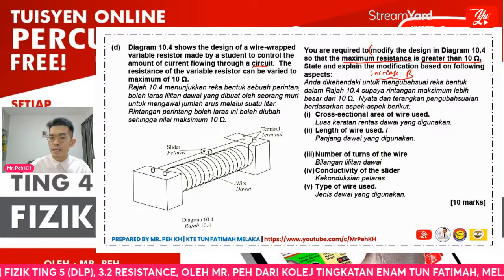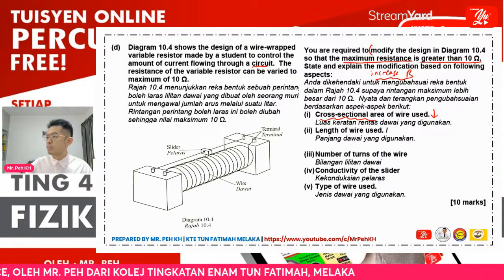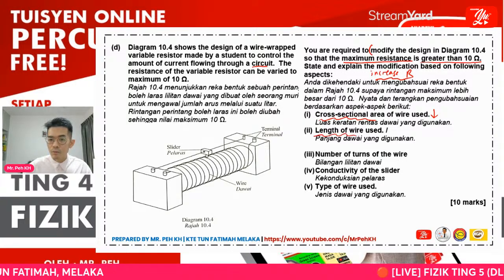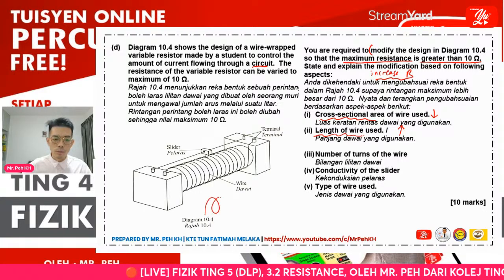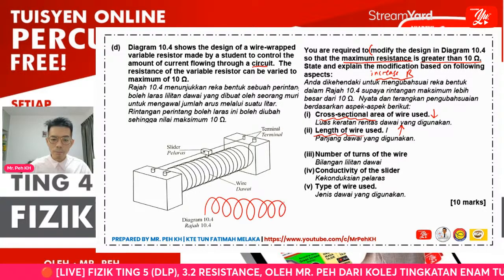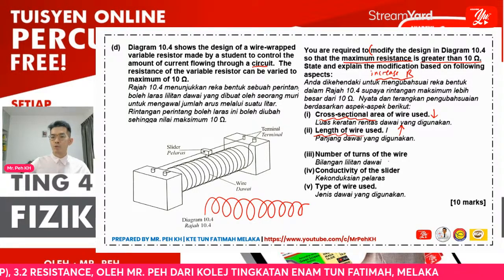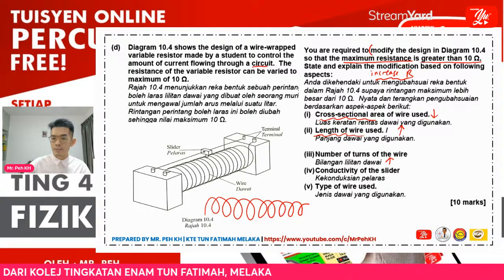Since we want to increase the resistance value to more than 10, we choose a smaller cross-sectional area so that the resistance will be higher. Then the length of the wire should be longer. Then the number of turns: when the number of turns is more, the resistance will also be higher. So we want more turns of wire.